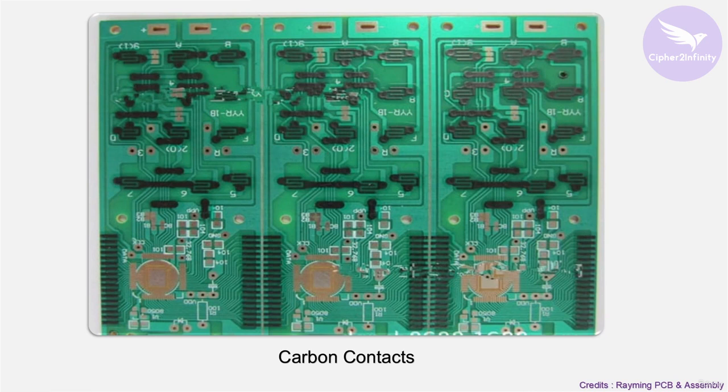So you have to tell the PCB manufacturer at what location, you have to highlight that particular location in your PCB, and you have to tell the special instruction to the PCB manufacturer that I don't want any kind of plating in this particular region, and you have to use the peel off in this particular region. Okay, so let me go back to the website now.